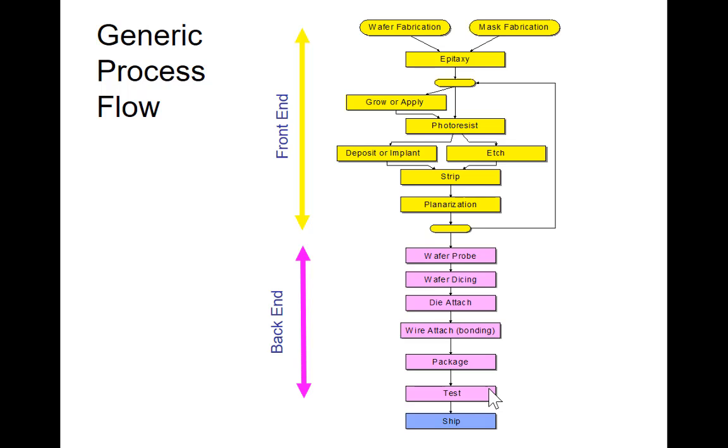And then so now you have your wafer. Then you begin to put one layer, you prepare it, polish it, etc. And then for each of the layers that you want to do, you do these few steps. You put some material on the top of the wafer, oxide, and you do CVD.